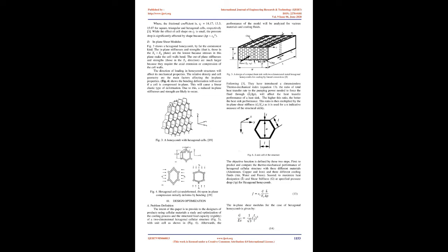2. Theoretical background. A. Relative density. The properties of a honeycomb or foam depend, above all, on its relative density. Relative density is the ratio between array density and solid density, the fraction of solid space in the structure. Every structure has its specific relative density depending on cell type, orientation, Fig 2, and cell dimensions. Generally speaking, cellular solids have relative density less than 0.3, and it is given as equation 1.